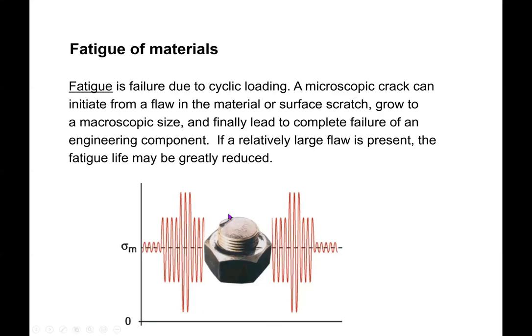Okay, so this is showing a bolt head that cracked in brittle fracture. This region over here, you can see that's where the fatigue crack was growing. This would be at the bottom of one of these notches, right, where the stress has a higher intensity. And then once this reached the critical crack size here, the rest of the sample is just a fast fracture case.